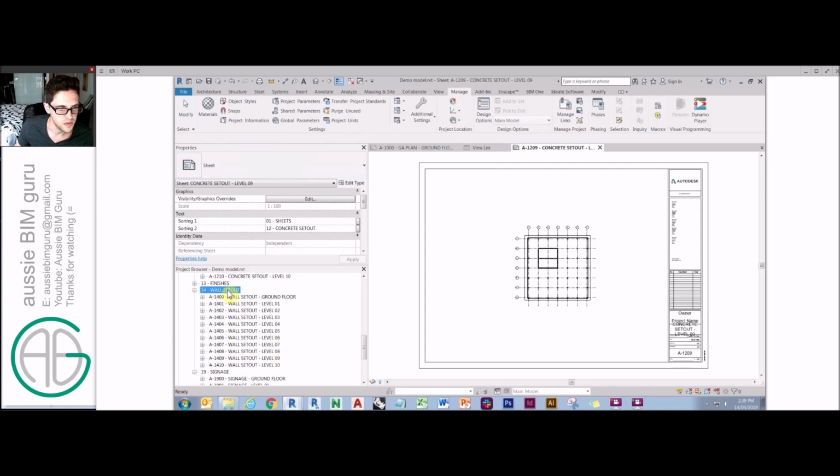A game changer for things like tower design, where you've got multiple plans all positioned the same way. If you had a project where you've got particular zones that are all positioned a little bit differently, you can do separate runs of the same script, or you can configure your script to recognize things like scope box correlations to view names to sheet names, so that you can semi-automate placement depending on how things are named in relation to each other. But it's a little bit more complicated.